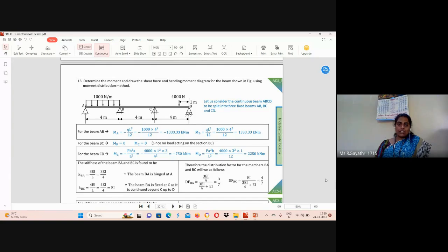Support D is also simply supported, but here support B may experience load from support A. Similarly, support C can experience load from support D. So we can't ignore bending moment. Using the normal approach, bending moment at every simply supported end will be 0, but here we need to go one step extra. We need to use the three moment equation to find the bending moment at intermediate joints B and C. Okay, what is the equation?